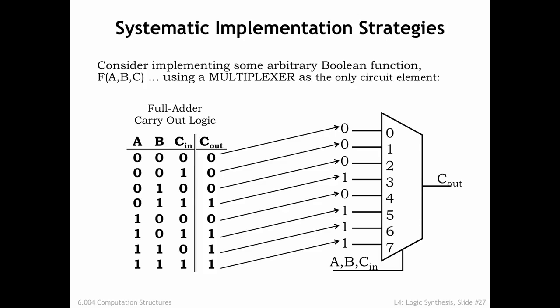Think of the MUX as a table lookup device that can be reprogrammed to implement, in this case, any 3-input equation. This sort of circuit can be used to create various forms of programmable logic, where the functionality of the integrated circuit isn't determined at the time of manufacture, but is set during a programming step performed by the user at some later time. Modern programmable logic circuits can be programmed to replace millions of logic gates. Very handy for prototyping digital systems before committing to the expense of a custom integrated circuit implementation.